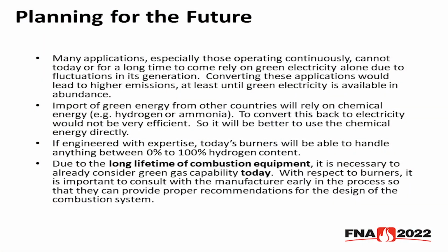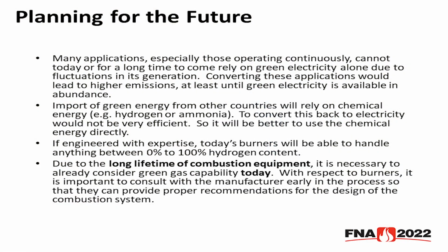The U-tube, for example, so we said it's designed to operate with a long, lazy flame. Hydrogen burns with a very short, hot, intense flame. So you're going to shift the temperature profile inside that tube to a place it wasn't intended to be. So from the first bend there back to the burner tip, basically. And that can lead to overheating, failure, other uniformity issues. Not to mention, hydrogen burns a lot hotter than natural gas. So typically that would lead to even higher NOx emissions.